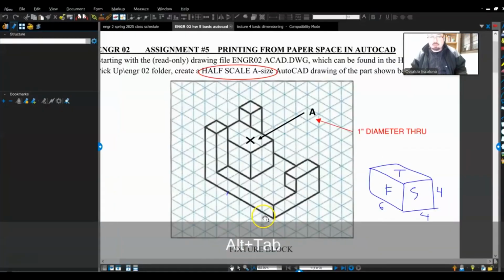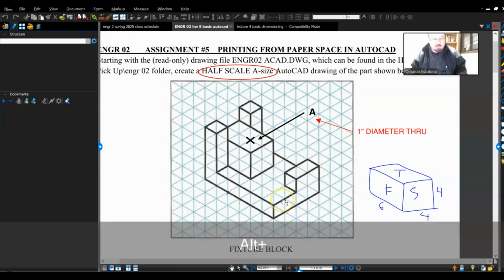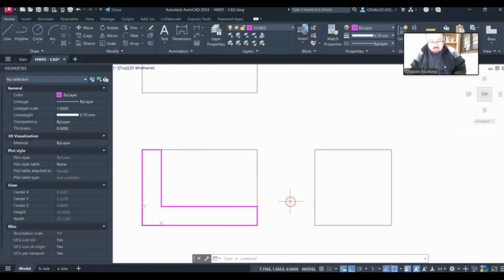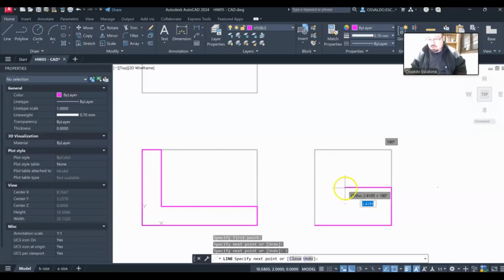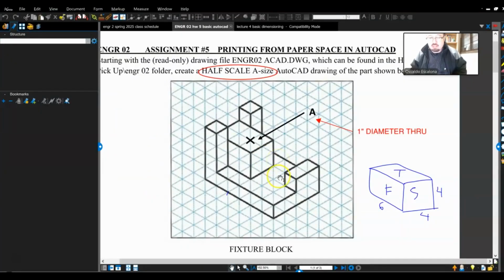Okay, let's go back. I'm going to do the side, which seems to me I have something also in terms of height. I'm going to go to the side again, L for line. I'm going to come here, come there, and move up 2 units. I'm going to move 2 units down, 1 unit down. I want to get to the perpendicular, and then I'm going to move down. See, that's the beauty of having F8, because you just go straight and give the distance.